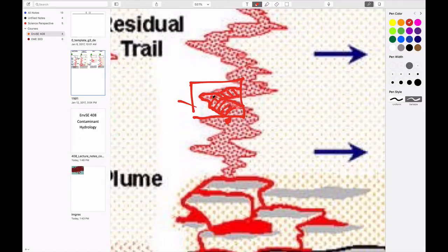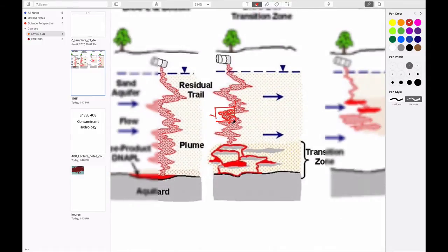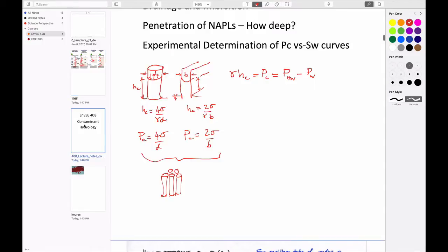We could look at the relative saturations of those. And that's a much more interesting question for us to know, because one, we'll find out that this saturation says something about the permeability of this material, in other words, to water going across it, which we'd like to know. And it also says how much stuff is in place in the subsurface and how much we'd have to remove if we want to make it pristine again. And so that's the kind of question that we would like to answer.